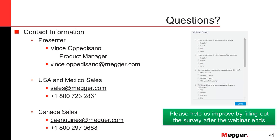It's not a clear explanation because it's not a very easy concept to understand. But I typically raise the stability setting to 99.8 or 99.9 before reading. So instead of 2, I would set 10 or 15 seconds. And then I get valid readings. And you know it's wrong when your V curve starts to go out of shape. I hope that's answered that question.